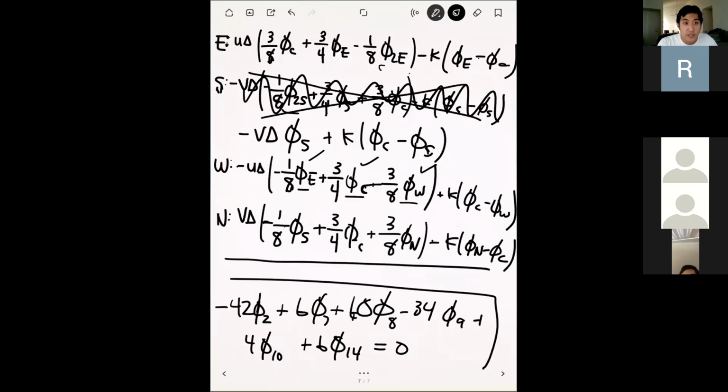So that's it for higher order schemes. In a nutshell, what you're doing is basically any term that has a convection in your governing equation, you're going to replace it with a scheme that's more accurate than basic central difference. But everything else you're going to keep the same. So if there are no more questions on that,